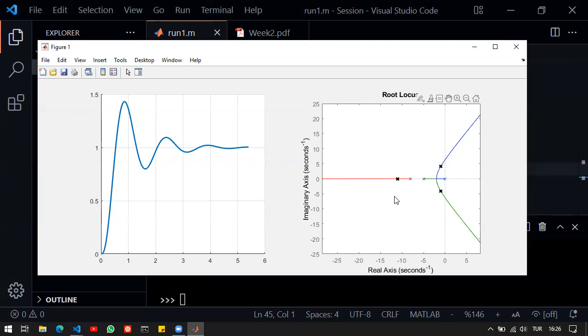Now, this is a good strategy. This is a good root locus because of our strategy, because of the fact that we have only the second-order part here to choose, and we want them to dominate this behavior. And luckily enough, two poles are in this vicinity, and one of them is approaching negative infinity, or it just goes further and further away from these two poles.